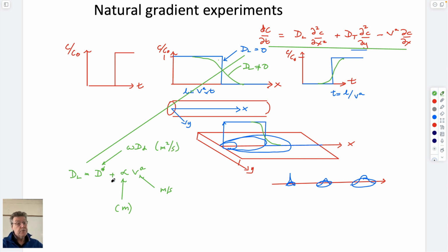We talked last time that this is always a constant and becomes dominant if the velocity is 0. It'll be mainly by diffusion, and if predominantly it's by advection, this term will be small relatively. It won't change, but it'll be very small relative to this term, and so we'd want to know what these terms are that go into this.